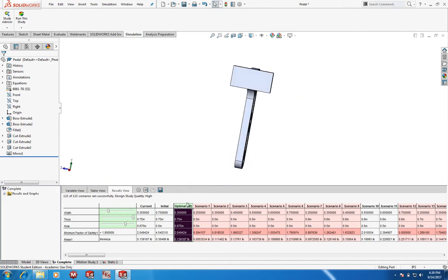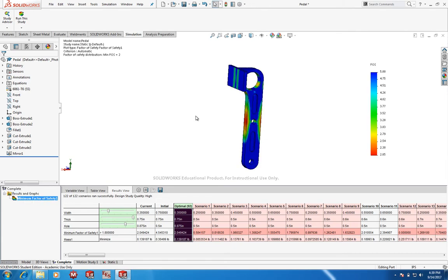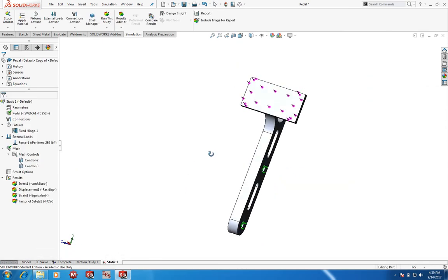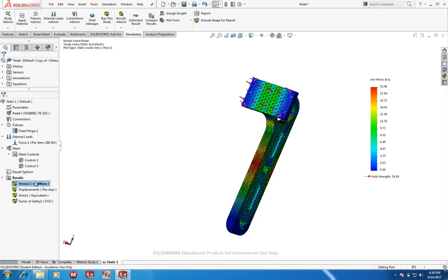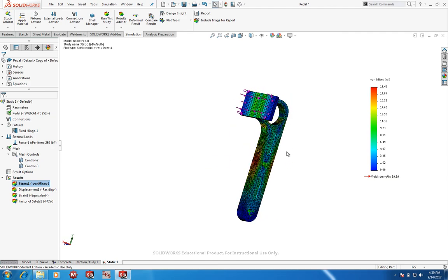Now, the cool thing about this, since it ran all those stress calculations, is that if you come over here, we see you have your goals, right? So there's your factor of safety plot, 2.05. We had it filtered off at 5, so that's just how we left it. But if you want to see everything else, you can go back to your static study, and it keeps that geometry, okay? So it updates your part geometry unless you decide to go back to the initial. So all of these stress parts, or stress files, are going to show your results with the new geometry.